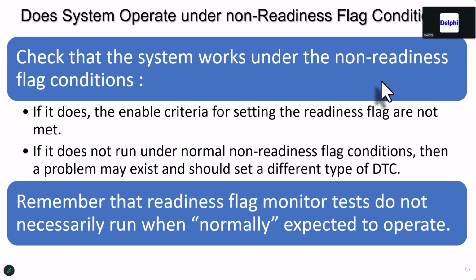And the FTP, which is a reporting component. If you take away anything from this class, always ask yourself, what is the reporting component for that particular monitor? In EVAP, it's the FTP. We know for the cat, it's the O2s, front and rear, air fuel sensor, oxygen sensor, could be air fuel and air fuel if it's a Toyota. But those are the reporting components. If they're not working right, then you may not be able to run the test. So you got to run the verification to make sure that they're working to a point. So I call this non-readiness.